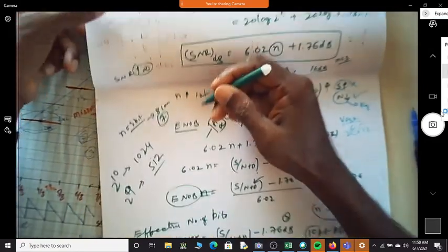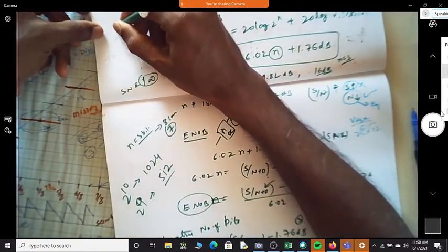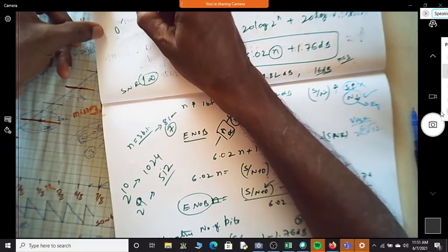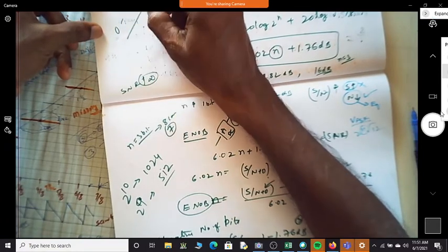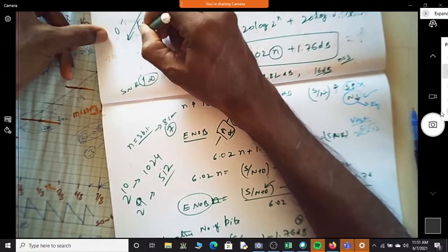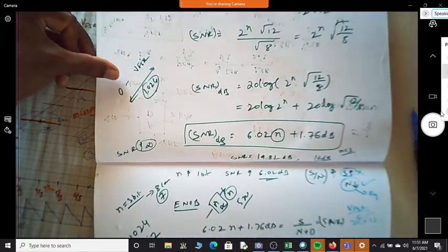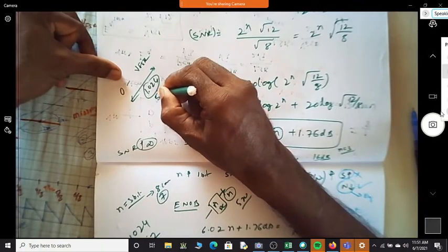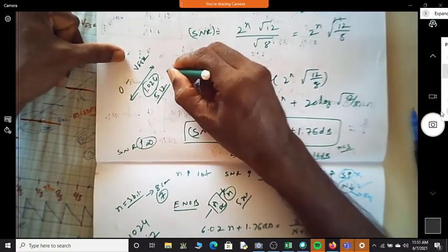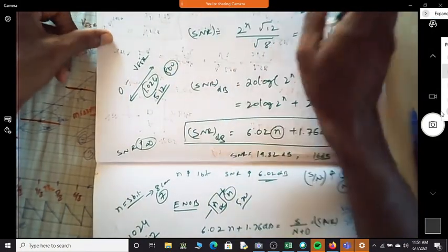Meaning, if the input voltage is 0 to VFSR, you would have ideally got 1024 different combinations. Because of more error, you will get only 512. Another 500 codes will keep missing.